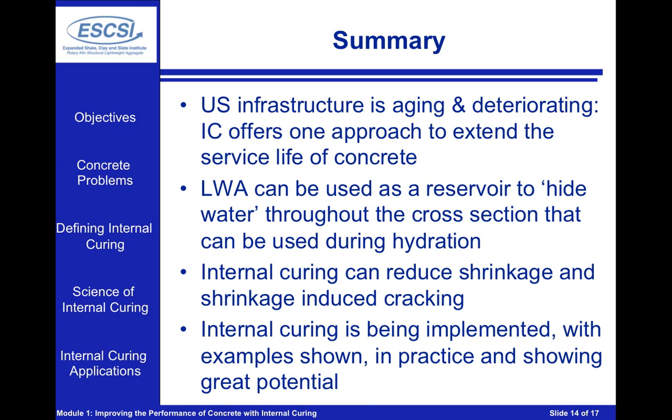So in summary, what we've really been able to see in this module is that the infrastructure in the U.S. is aging and deteriorating, and we're going to be repairing and replacing a substantial portion of this infrastructure. Internal curing really offers us one approach to extend the service life of concrete, and the idea here is we can really use internal curing with a lot of our high-performance concretes to really get the most out of those concretes because they may be prone to cracking.